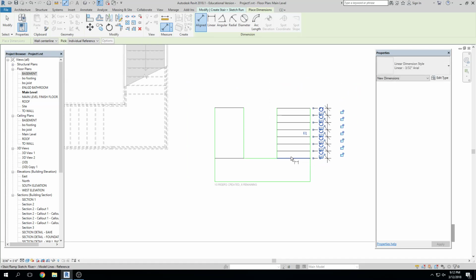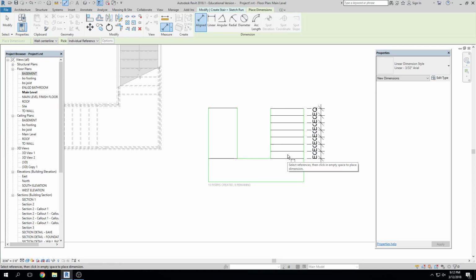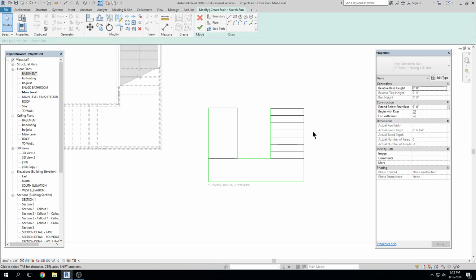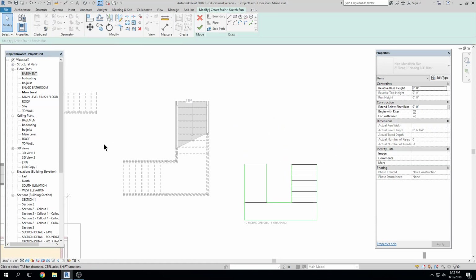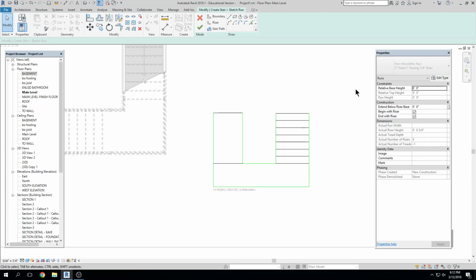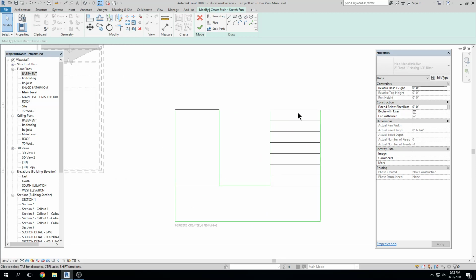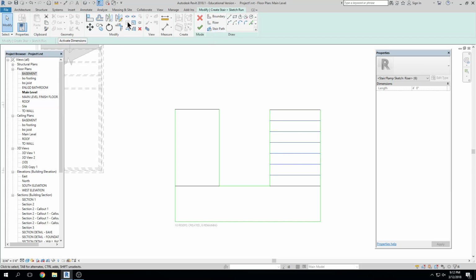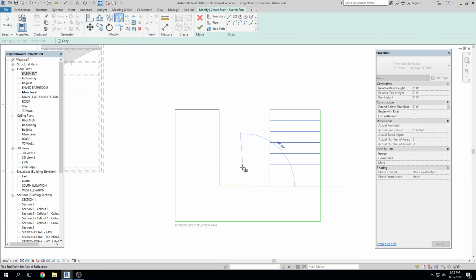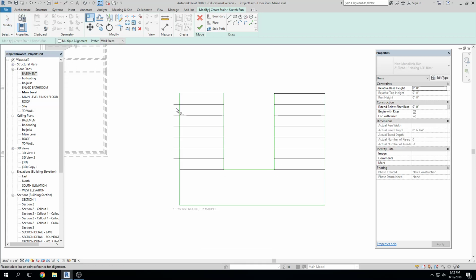But the thing about it is that you rarely get just a single run of stairs. I mean, that's very rare in a project, right? And usually the stairs are somewhat limited by the architecture around them. And so the problem with this is that you're creating these clunky, unmanageable pieces that you then have to fit into this opening that is custom in the first place. And so you somewhat have to go back to this idea of a sketch to get them to work, funny enough. I'm totally about automation. I mean, if I could do it, great. But I end up having so many problems with the other stairs working, right, that I ended up just going back to this method.